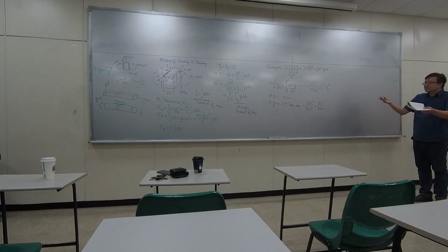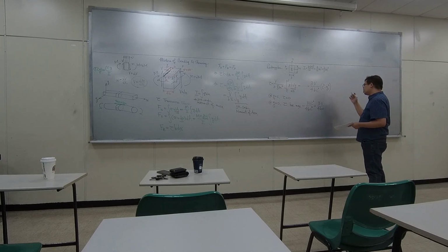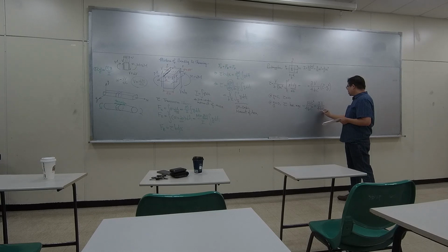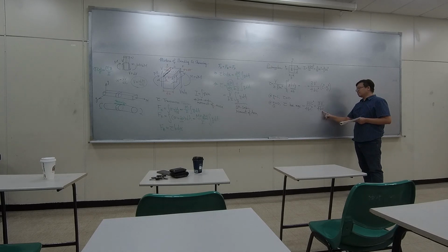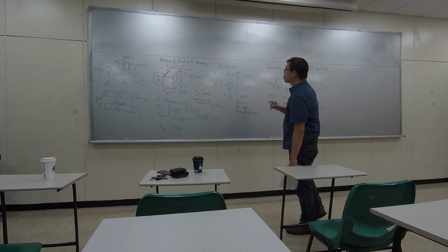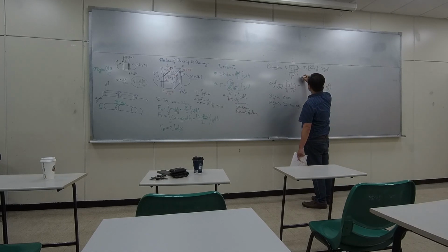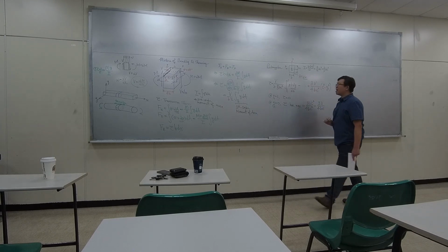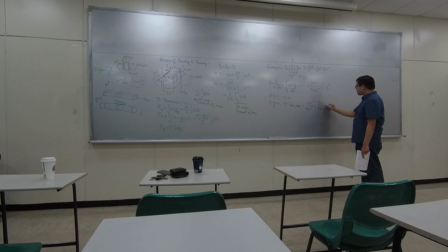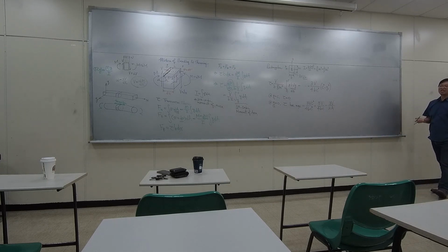Some of you may study this and find it in a different form, because usually they want to put area at the bottom, using the cross-section area. This geometry has a cross-section area of 2bc. If I define A as 2bc, then this is going to be 3V over 2A. So this is what you usually see from a book.